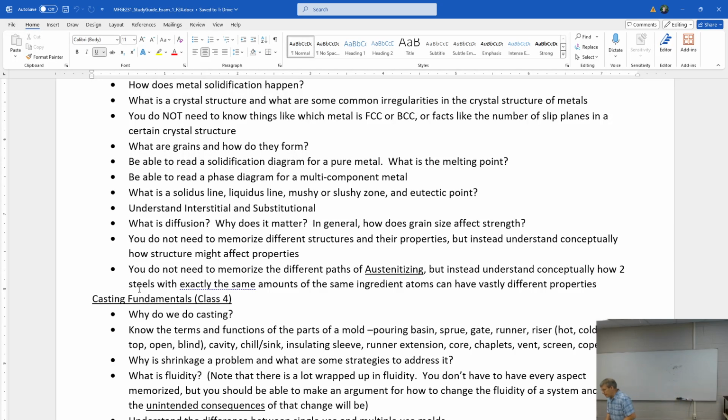So you want us to know what happens at slip planes? Yes. And how dislocations are stopped, and how the dislocations affect our material properties? Yes. So just to clarify, it affects the properties by increasing the strain? Well, it limits more strain from happening.